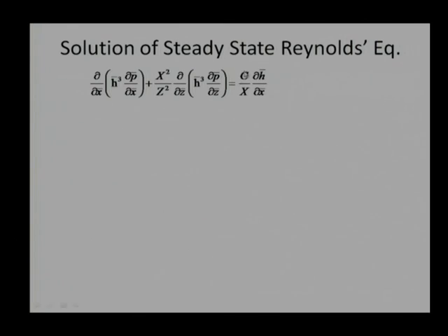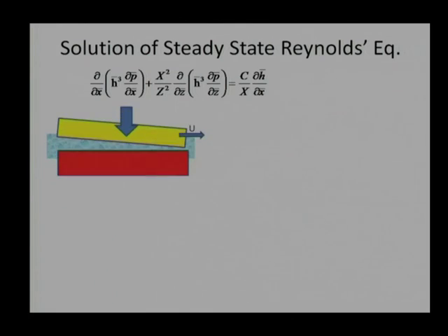indicating that the whole bearing surface can be divided into a number of nodes, and using Taylor series we can estimate the pressure profile over the bearing surface. We considered only the steady state Reynolds equation, where the time dependent term was neglected. The dH by dt is negligible for a steady state Reynolds equation, and we considered wave action. Assuming the surface is rigid, there will not be any pressure generation due to variation in surface velocity.